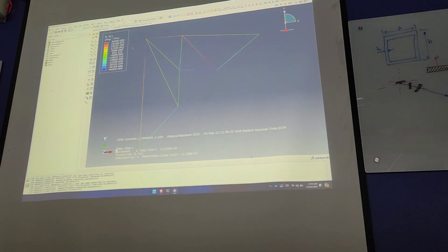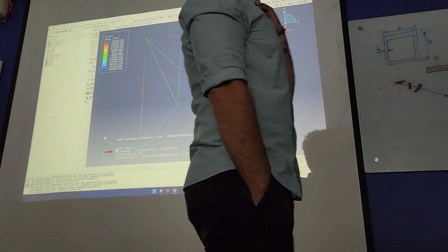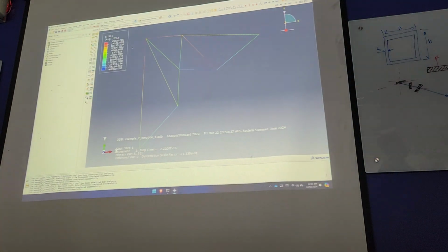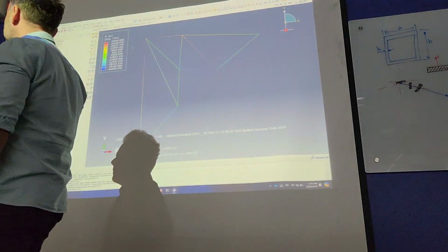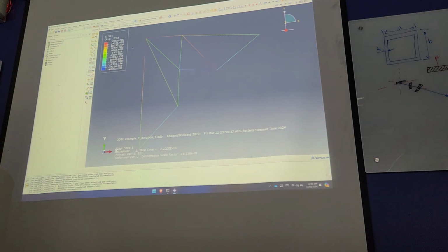Tensile and yield is different, right? I think it's tensile strength and yield strength. No, yield strength is how much the stress can bend. So tensile stress is how much the thing is pulled. So define the yield strength. The factor is a 3 parameter. Yeah, so you need to take your yield stress from the material, which is for example 800. So you need to divide by 3. So then when you have your bending stress, your bending stress cannot reach that figure divided by 3.